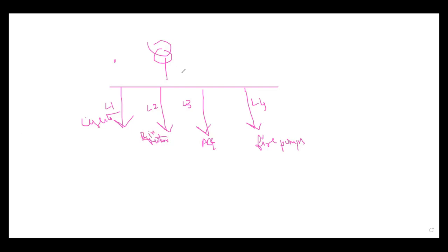Now in the transient analysis, what we will do is, suppose all the loads are in service, means all the loads are on. All ACs are on, and the fire motor is also on.